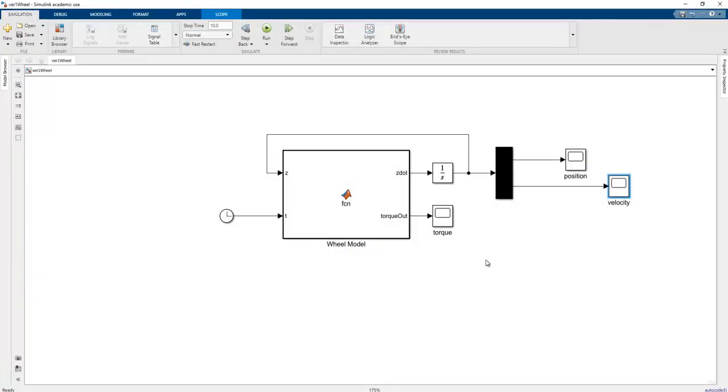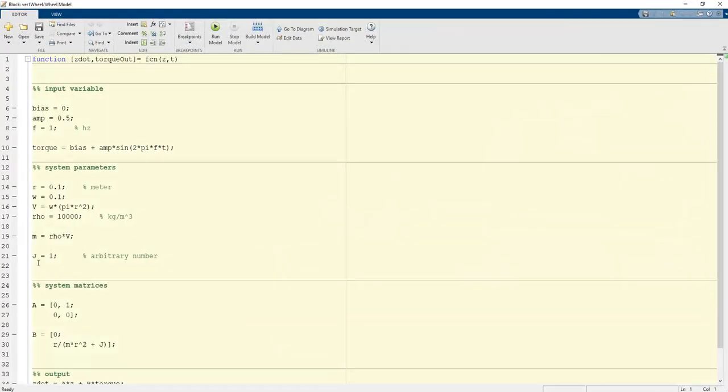And so what's the outcome of this observation? The observation states that the J value directly affects the system time response. If we want more velocity in a real life application, this J should be smaller than the normal one. If we want a smaller velocity in a real life application, we should choose the J value bigger than the normal one. If we have the bigger J value, we have the small velocity, and if we have the small J value, we have the bigger velocity in that case.